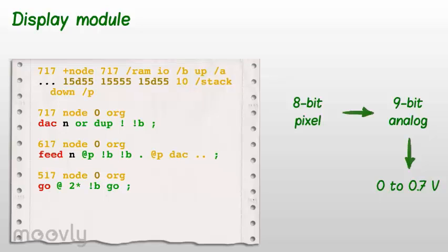However, we have attached all three analog VGA lines to the same DAC and therefore have three 75 ohm resistors in parallel, which gives load resistance of 25 ohms only. For such a configuration, 0.7 volt can be achieved with DAC value of 511. This is the top of DAC range. The scaling factor is thus 2 and the pixel value is simply left shifted by 1 bit.